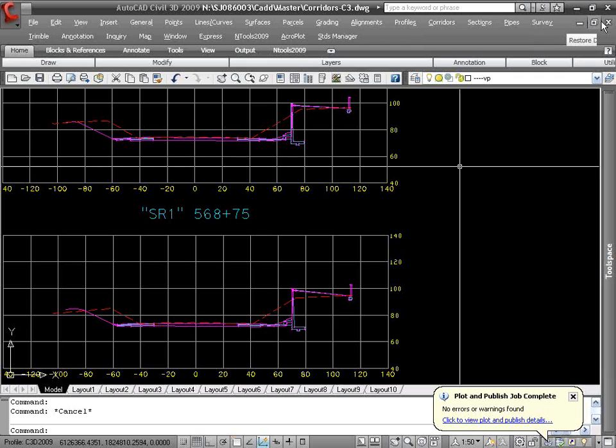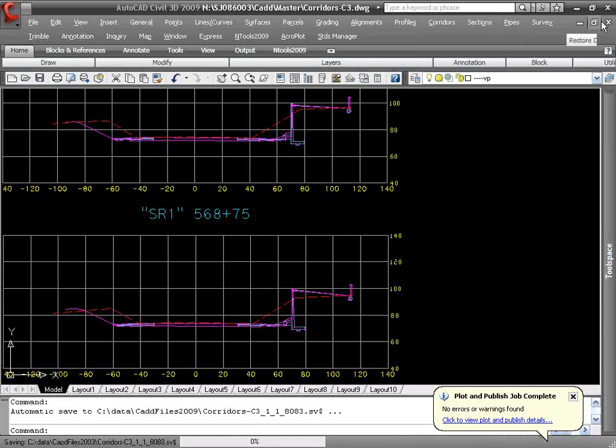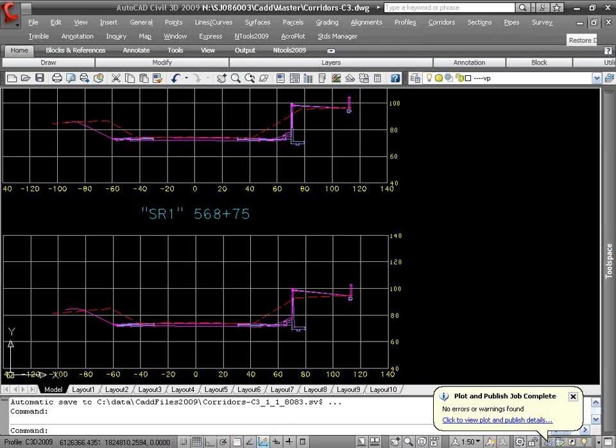You saw that listing that Brandon had showing all the assembly properties and the construction, how they were all in order. If you delete one out of the middle of the list, it'll close up. You can't edit that list, but you actually physically edit them in the drawing. And we had some that just didn't close up right, and we ended up having to delete them and then rebuild those one or two sub-assemblies.